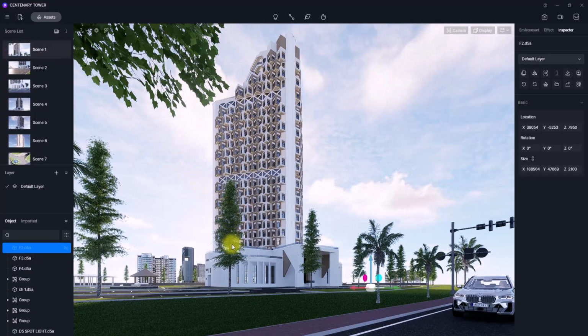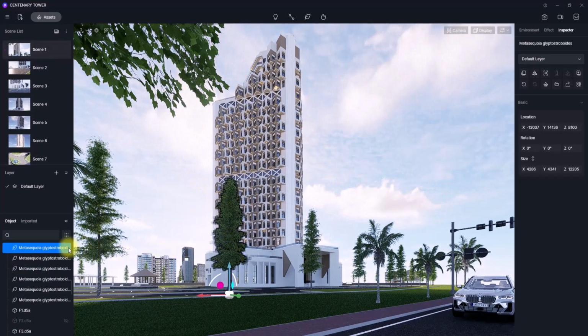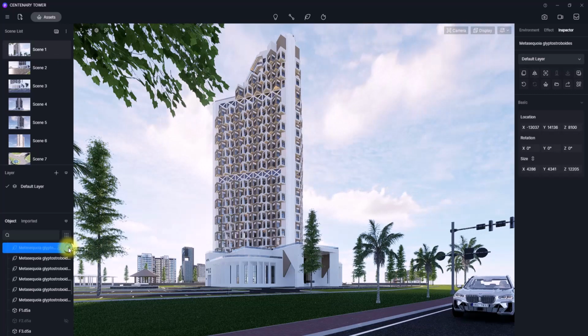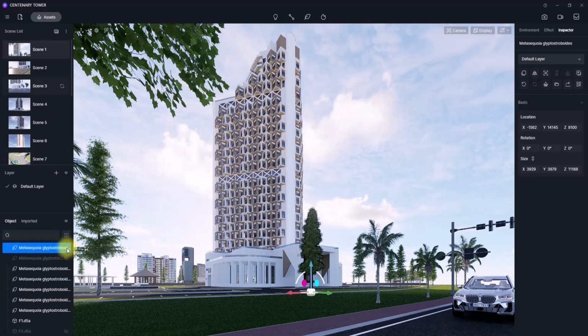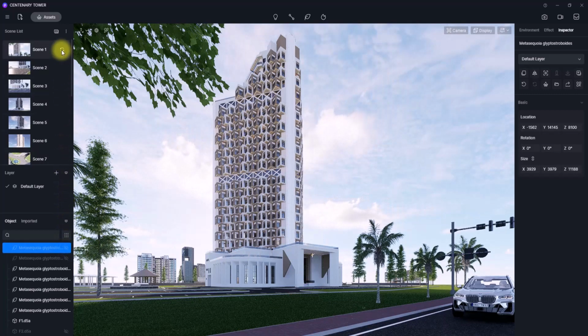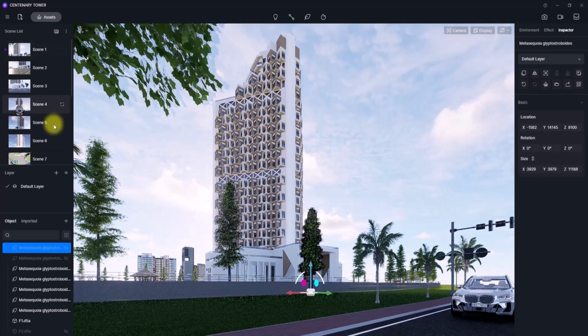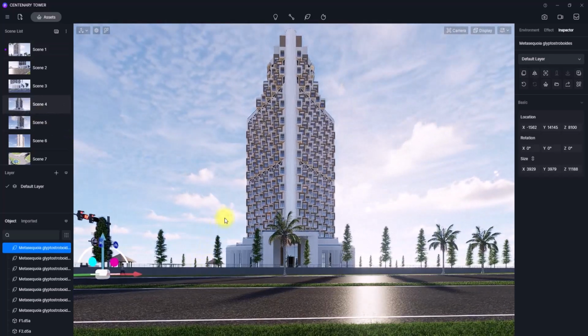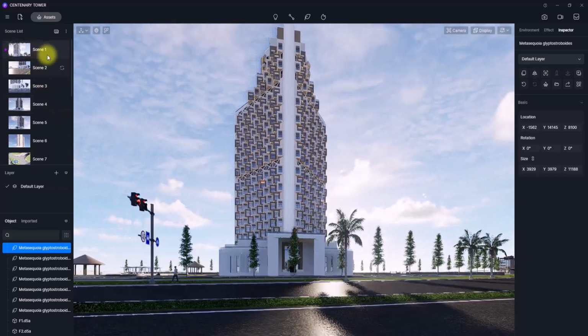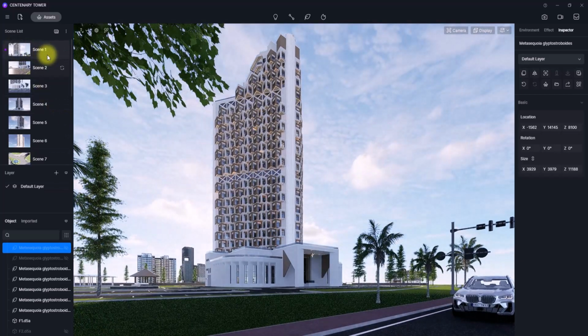We could do the same for this coniferous plant. Then we're just going to go here, hide it in view, go back, update it, do the same for this, hide in view, update it, and we'll actually have a view where these objects are hidden, but if you go to another view, it will actually return back. So it kind of gives you this 3D illusion, so you can hide objects in view just the way you can hide it in Revit. So it actually allows for a lot of versatility in your rendering environment.